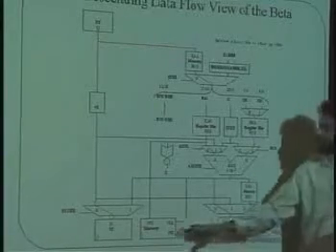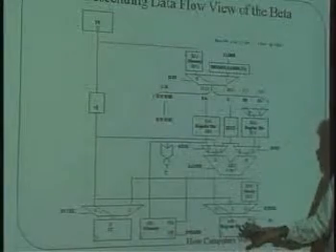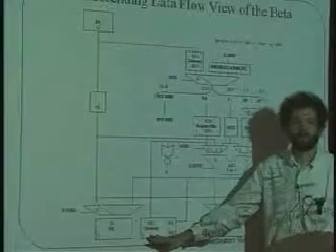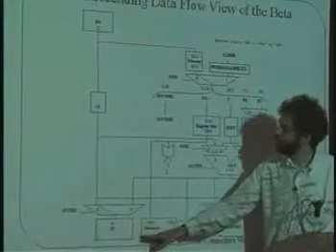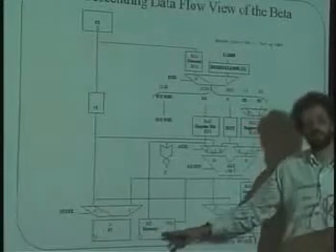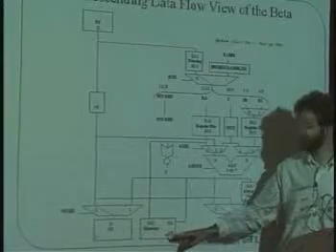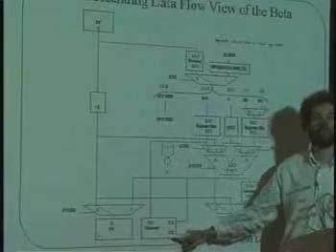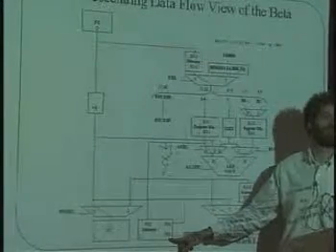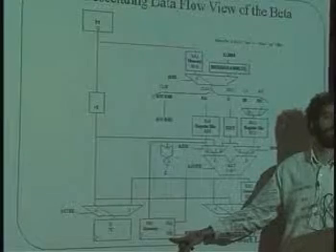On the other hand, we have two other portals here for writing, one being a portal into the register file, the other being a portal into the big slow memory. And when the clock goes off here, sometimes we're going to write into the big slow memory and sometimes we won't. That's determined by whether the WE here is high or low, whether it's a 1 or a 0.